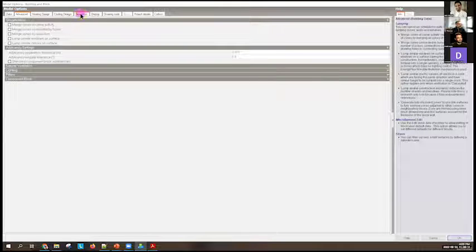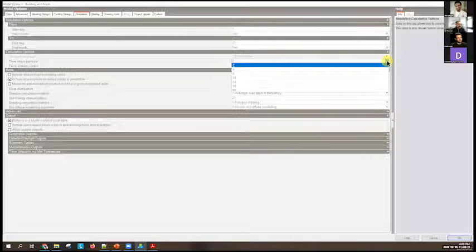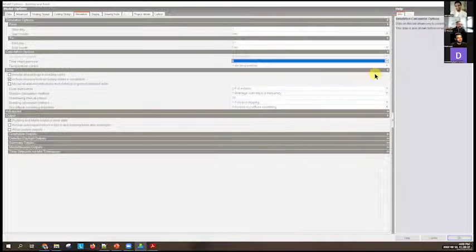Now, if you go to the simulation tab, there are a few things to change here. We want the time steps per hour, the number of times DesignBuilder EnergyPlus calculates this. You want it to be 1 every 10 minutes. Now that's a kind of balance between speed and accuracy. Okay, you can have more, it takes more time, but I think this is good enough.